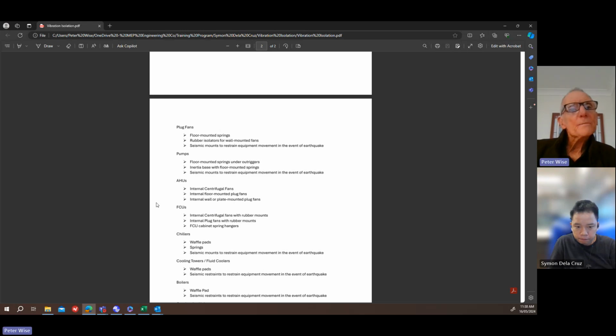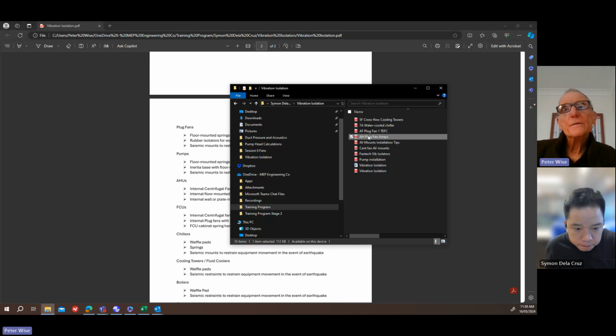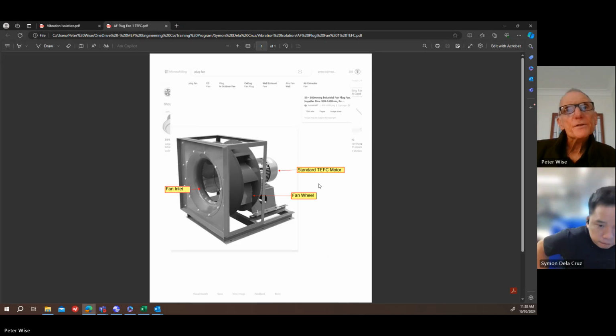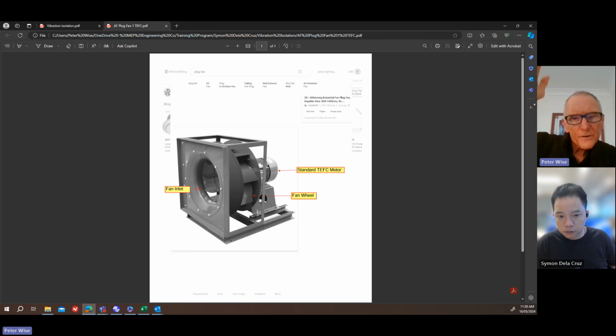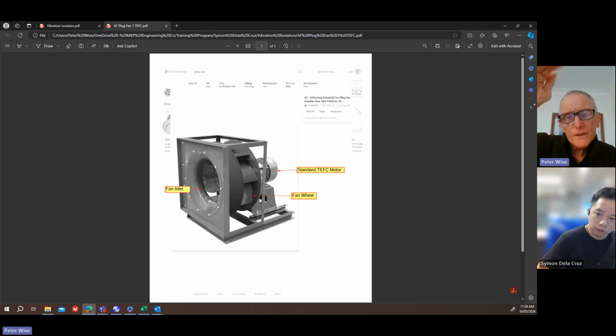And a plug fan inside is another one. This is just a plug fan that you would put inside an air handling unit. It's an open setup, so you've got to put this inside a sealed chamber. So the air inlet here has to be up against the wall. So you'd have a flexible connection between this flange and the wall of the air handling unit for the inlet, and then the outlet side is just a sealed box. And then you can have your discharge wherever you want it. You can come out the top, because there's no ductwork between there and the discharge.